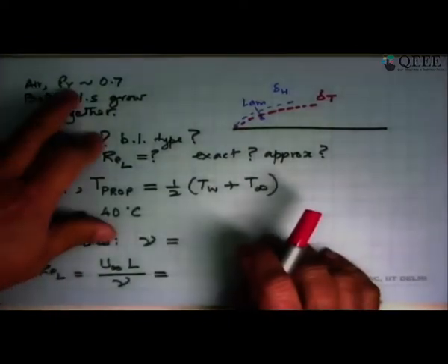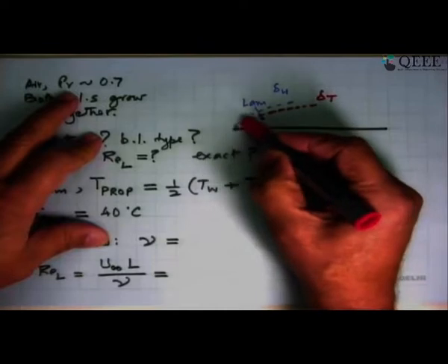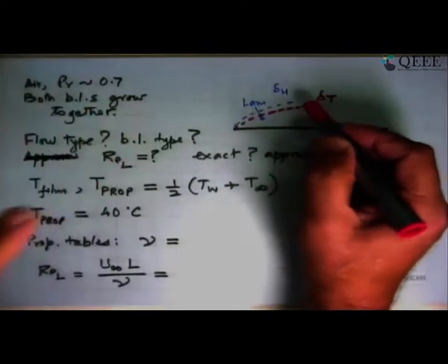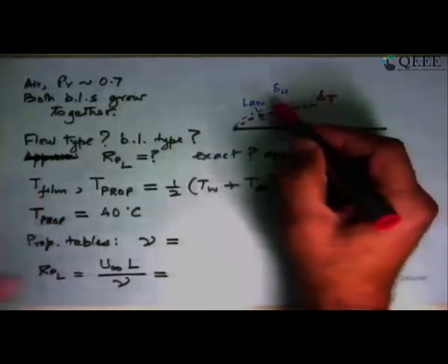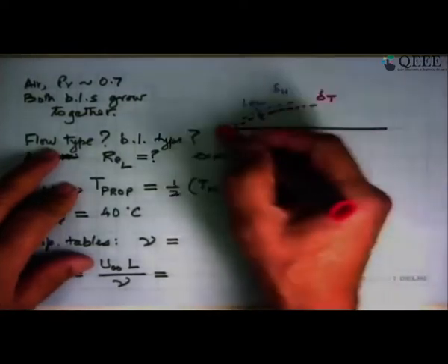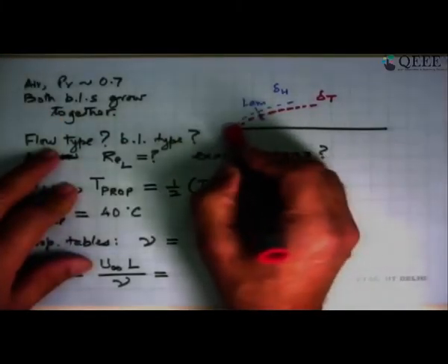And we said for Prandtl number 0.7, the hydrodynamic boundary layer, if it was like that, the thermal boundary layer will be almost like about the same size as the hydrodynamic boundary layer. So this is half the story we know now. They will both grow together. That is the second thing, because the flow coming here is very smooth and the entire plate is heated up.